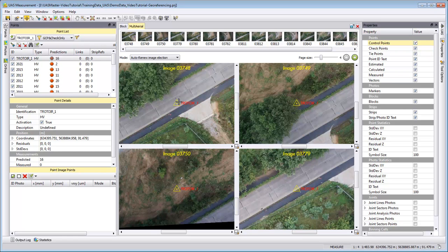We don't use high precision GPS here, so our GPS is something around 6 to 10 meters accurate. Additionally, we have height changes in the terrain. So the position of this prediction is somewhere around 6 to 10 meters around the control point, but it can also vary and go further away if our IMU is also not good and the camera is looking at a different position than we assume.